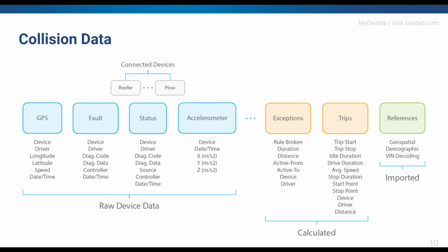And then the accelerometer, you see here actually the values in X, Y, Z. So you can derive this information in 3 different directions, and this is important to understand actually what direction means what. So the X direction is here the forward-backward movement of the car. The Y direction is the sideward movement, and the Z direction is the up and down movement.